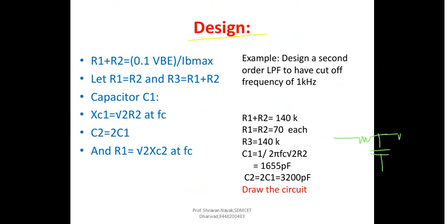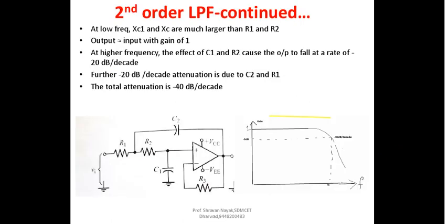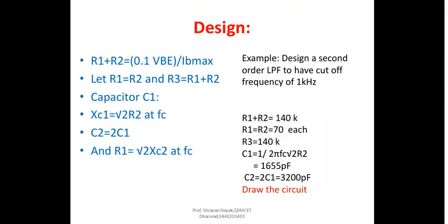Now referring to the diagram there, you have the total resistance R1 plus R2, right? That is the input resistance. These resistances R1 and R2 are evaluated as a single resistance using the very obvious formula, 10% of VB divided by IB max, right? So again, what is IB max and all, I am not going to repeat those things again. Several times we have come across this.